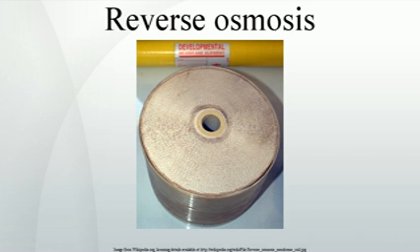Membrane assembly. The membrane assembly consists of a pressure vessel with a membrane that allows feed water to be pressed against it. The membrane must be strong enough to withstand whatever pressure is applied against it. Reverse osmosis membranes are made in a variety of configurations, with the two most common configurations being spiral wound and hollow fiber.